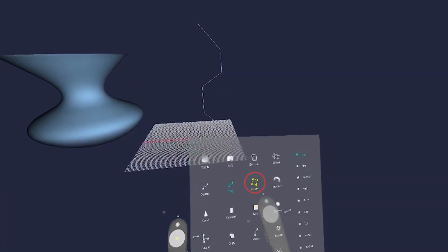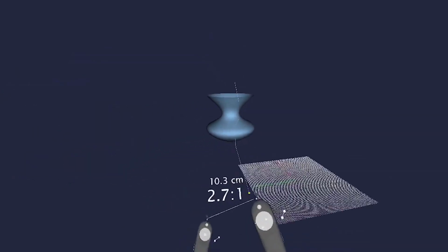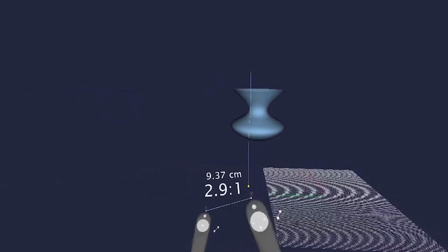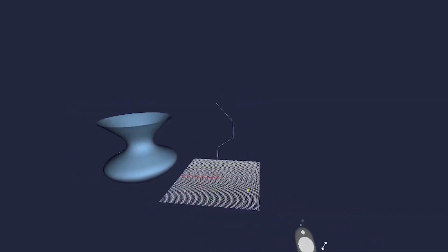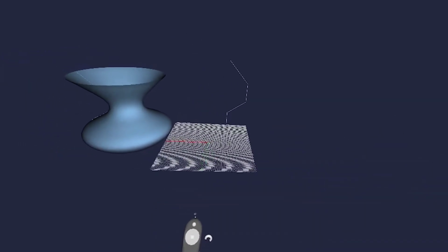Once you're finished with that, we can go ahead and adjust the points using the knot tool. Move the points in profile, making sure to keep everything planar. Once you're happy with your profile, we'll go find the same revolve tool and grab the profile.